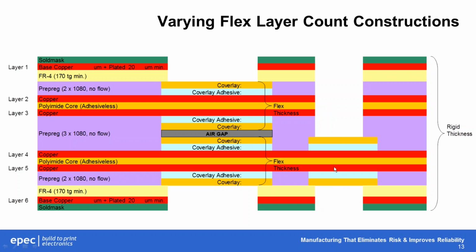The primary advantage of this is in the reduced flex section, given that the number of interconnects do not require the additional layers. By reducing it down to 2 flex layers only, you significantly improve the bend capabilities of this type of construction.